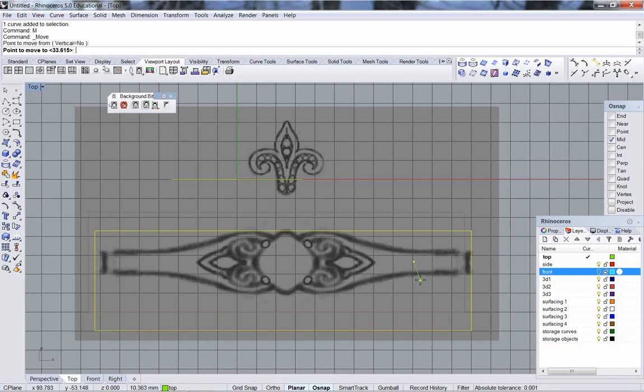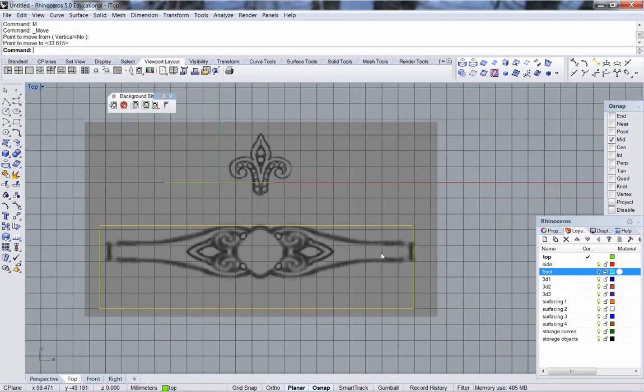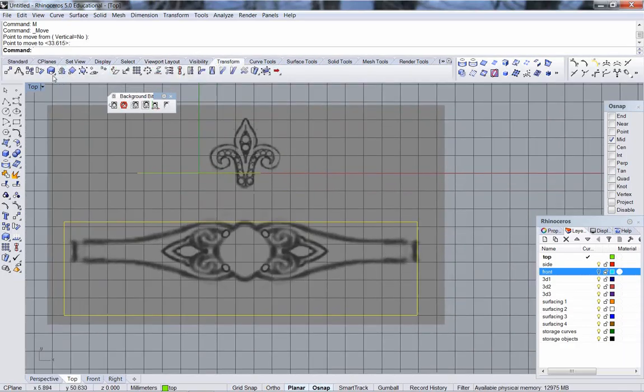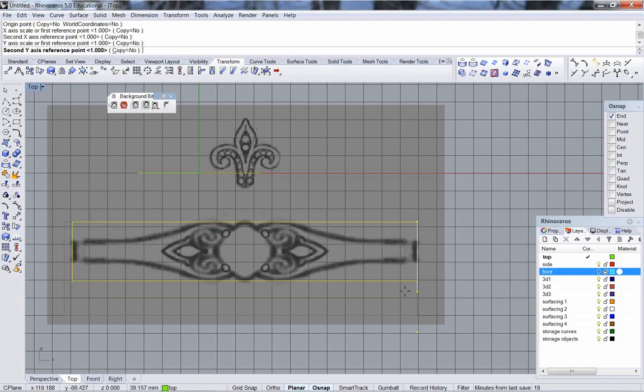I'm going to line that box up carefully now with the top edge of my design and the one side, and then non-uniform scale the box until it fits my design accurately. So in from that side, up from the bottom. Notice my origin point for my scaling was here, because that's the one place I didn't want to change. That's where you put your origin. For any scale command, you put your origin in the place that you don't want to change. Okay?